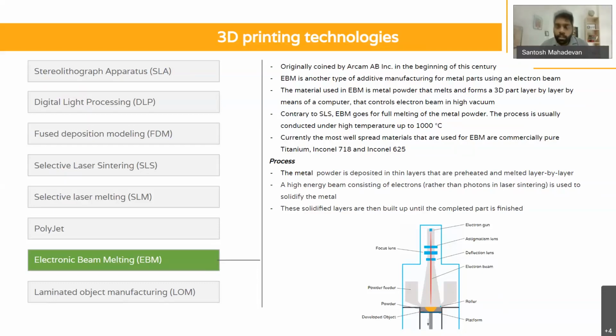And if we move on in the future to the days where we will be replacing conventional metal manufacturing with SLM and EBM, with a number of machines, right? So when you're creating each part, if you are going to spend, say, 10 minutes to correct the dimensions of a part created by SLM, over 8 minutes that you would be doing to correct the dimensions of a part created by electron beam melting, you're going to save 2 minutes per part.